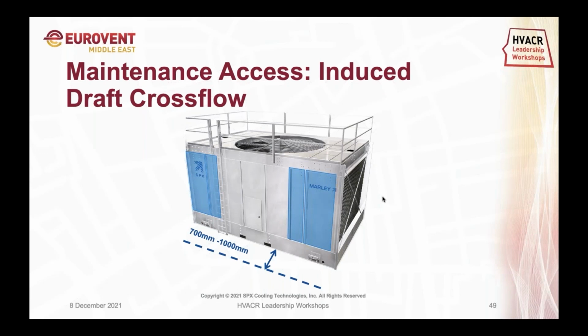Usually, not a rule of thumb, but usually it's between 70 centimeters to 1 meter to allow you to have the maintenance access for any potential maintenance, fills replacements, cleaning, etc. Have a proper space to enter the tower through the access door. So usually it varies from manufacturer to manufacturer and varies according to the dimension of that cooling tower.